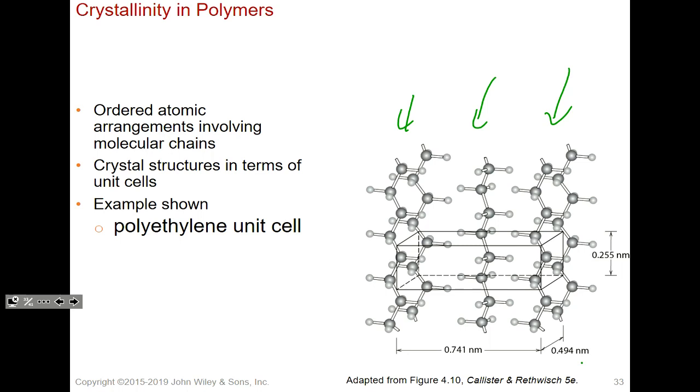And depending on how many repeat units you have, it will result in different crystal structures and different mechanical properties, like low density polyethylene for plastic bags versus high density polyethylene for water containers that are more rigid, or even the pipes that you see, okay? And it's really just all based on how you pack it in. And it results from cooling rates and also from just the pressure that you apply, okay?